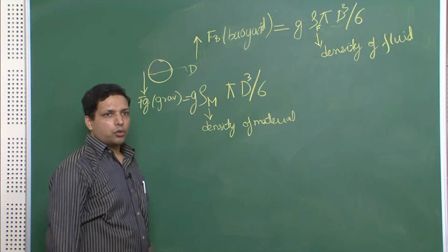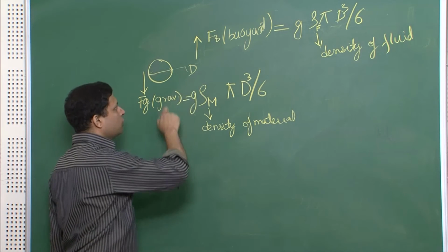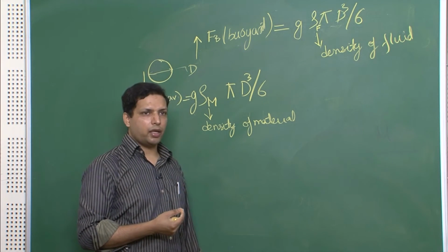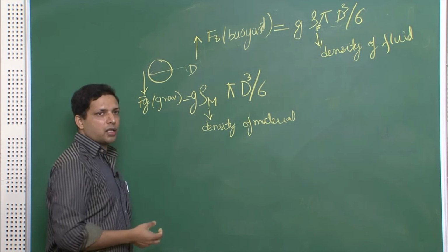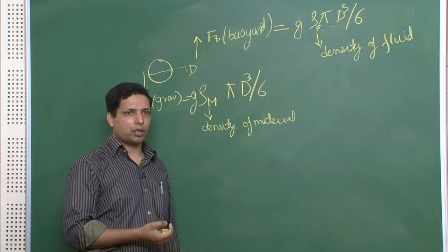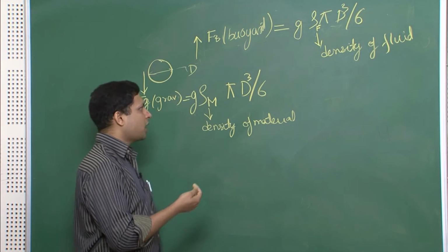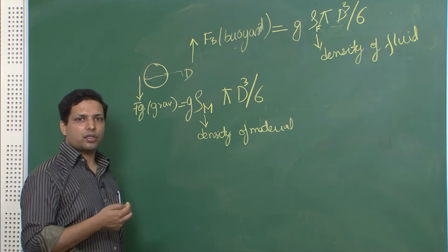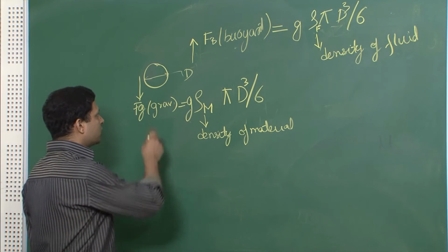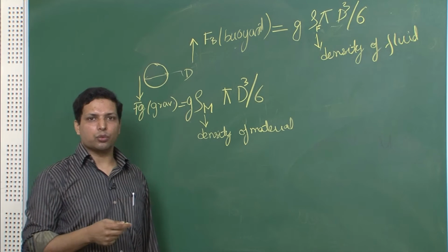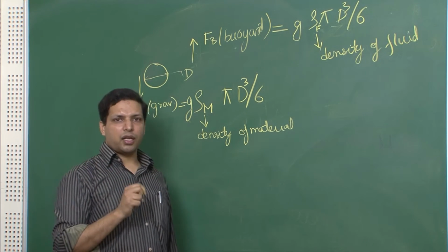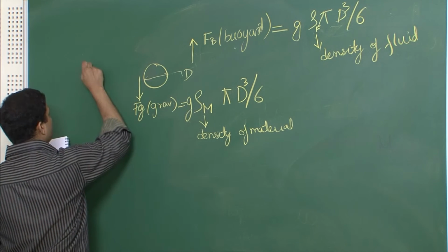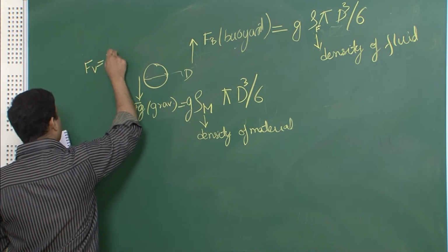Now, according to Stokes law, when a particle is allowed to settle in a liquid, in a fluid, this particle will start to accelerate to the bottom through the liquid. The viscous drag will start to increase, and this viscous drag will cause the speed of this moving particle to reduce, and eventually a steady state or a terminal velocity will be reached, and at that particular terminal velocity the viscous drag would be given by,